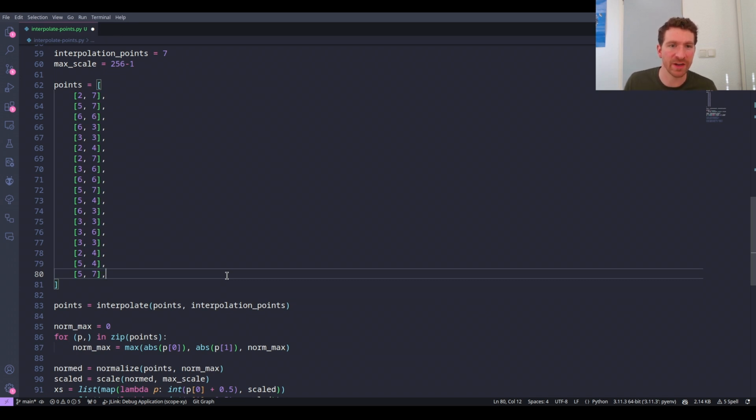So as you scale that up, if you start thinking about the frames per second that you actually want to show something at, then the more points you add, the more stuff you have to do in a single frame time, and the faster everything has to be. And as you increase the frequency, the speed at which you change things, you have to be much more detailed about how you're filtering, because you're putting in much higher frequency signals and you want to maintain this low frequency signal. So it becomes a little bit tricky to balance all of that out. This is a good place that I found to do this. So this is what we're going to be working with in the beginning.